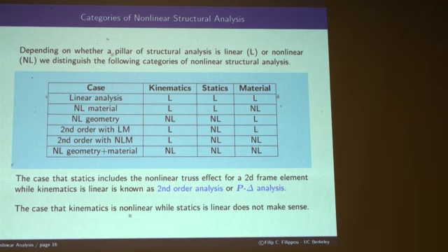As far as I'm concerned, if you are going to do a pushover analysis, you are much better off doing this or this. Obviously, in pushover you will do this. You're much better off. I don't have time to justify that. All I need to tell you is that the stiffness is tangent. You will see what the tangent stiffness brings. In this case, the stiffness that you have is not tangent. So if you turn on Newton-Raphson during the pushover, and you have a non-tangent stiffness, and you insist on a tolerance that is very small, you're going to be sitting there forever.